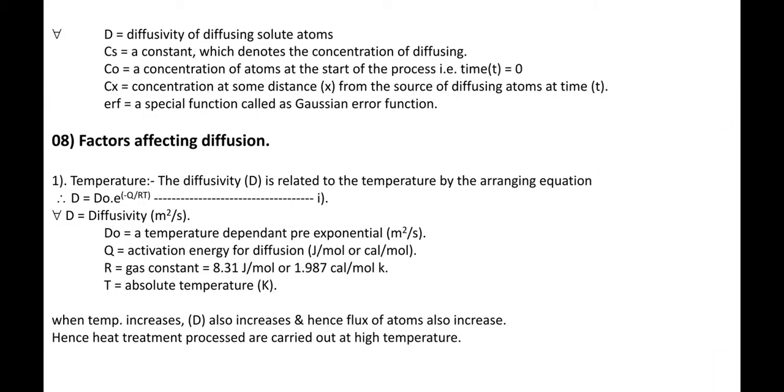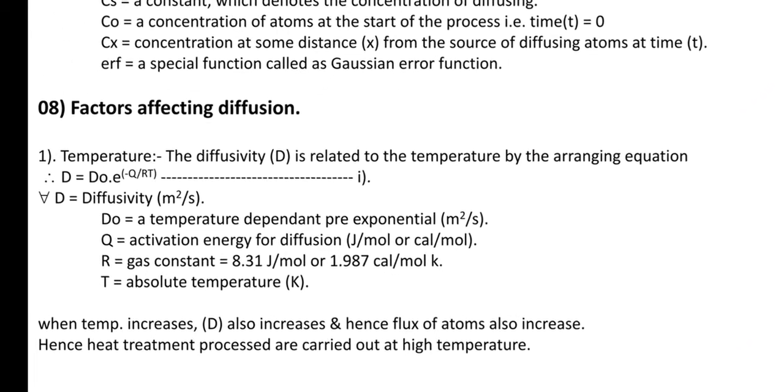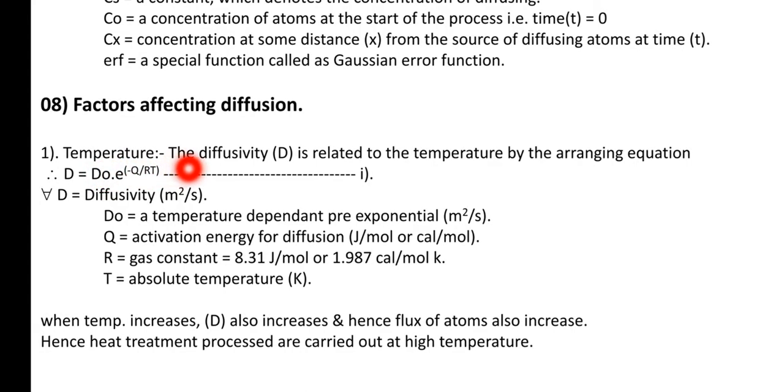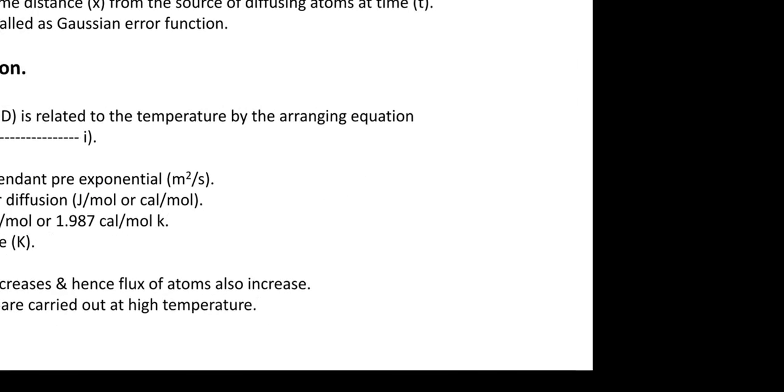Okay, now factors affecting diffusion. As the temperature increases, diffusivity also increases, or the flux of atoms also increases. It is given by the mathematical equation D is equal to D0 into e raised to minus Q divided by RT.